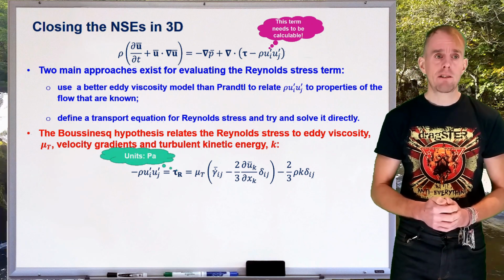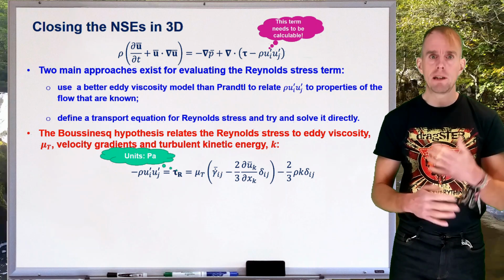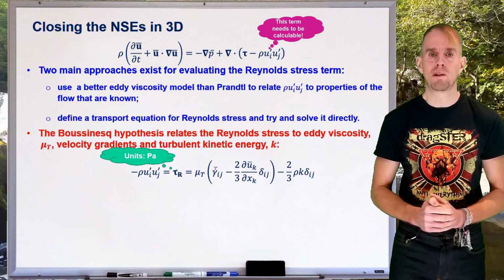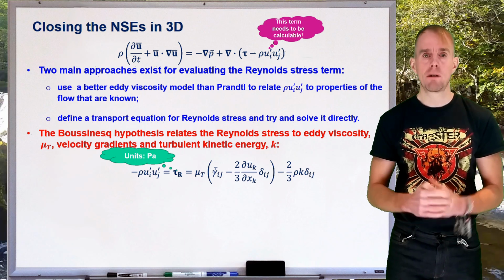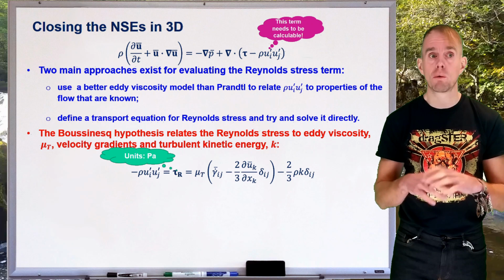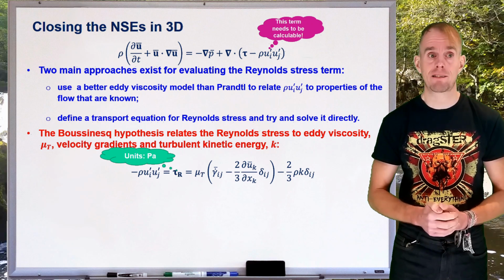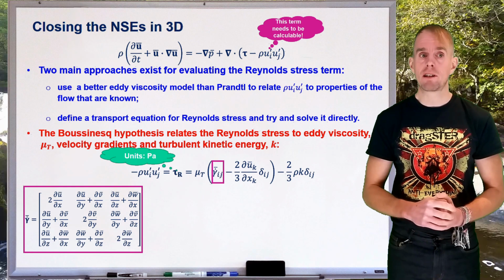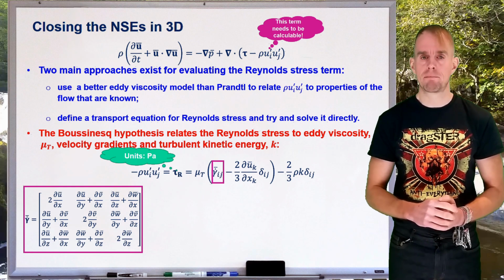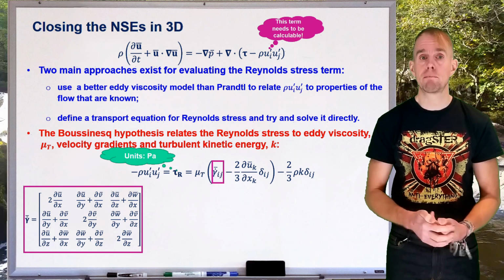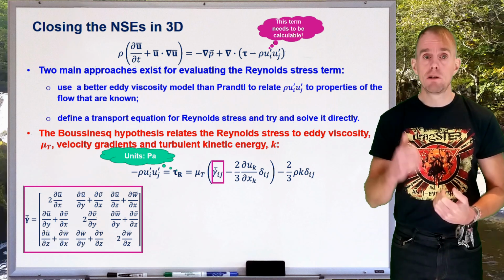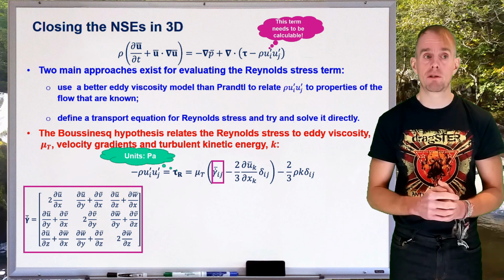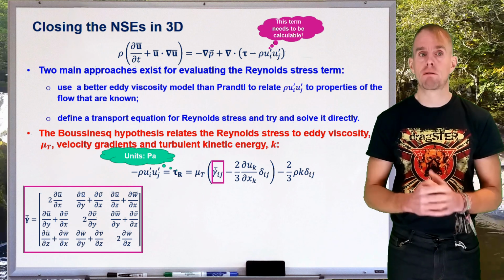So, let's have a look first of all at the dimensions. We need to have our mental model to make sure that when we calculate terms that we always have the right terms in the equation. We're dealing with stresses in Reynolds stress, and so all the terms have fundamental dimensions of Pascal. The first term in these parentheses is gamma dot bar ij. Gamma dot bar ij is simply my rate of strain tensor. You might have seen it on previous courses, such as a rheology course, written as bold gamma dot. And this is grad v plus grad v transpose.